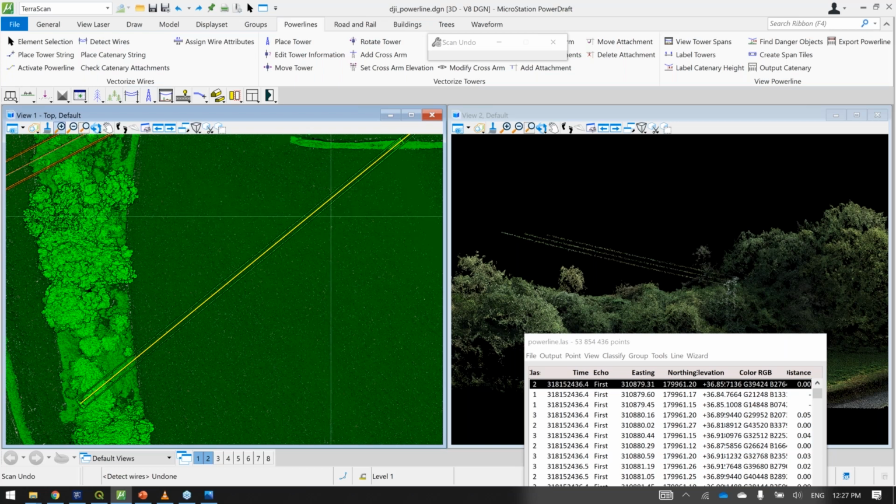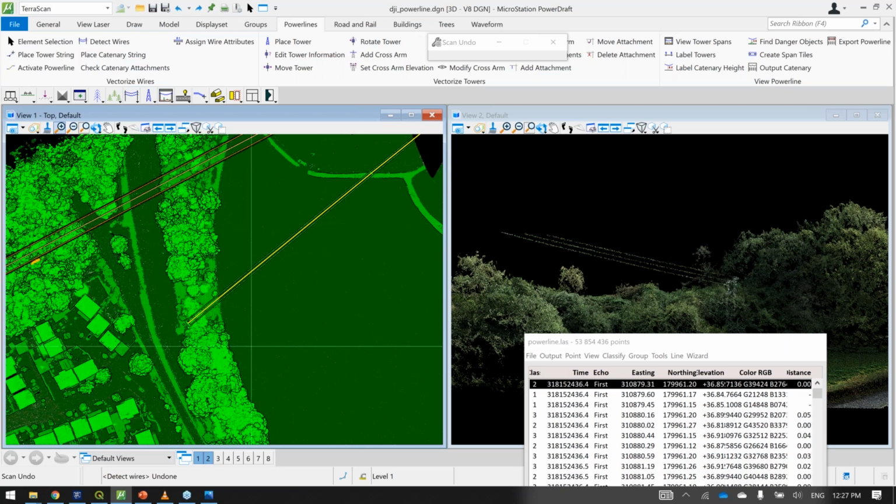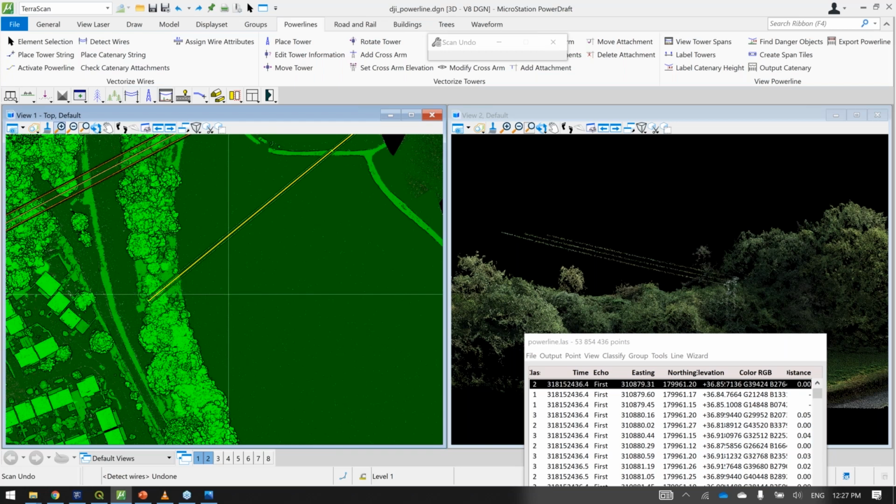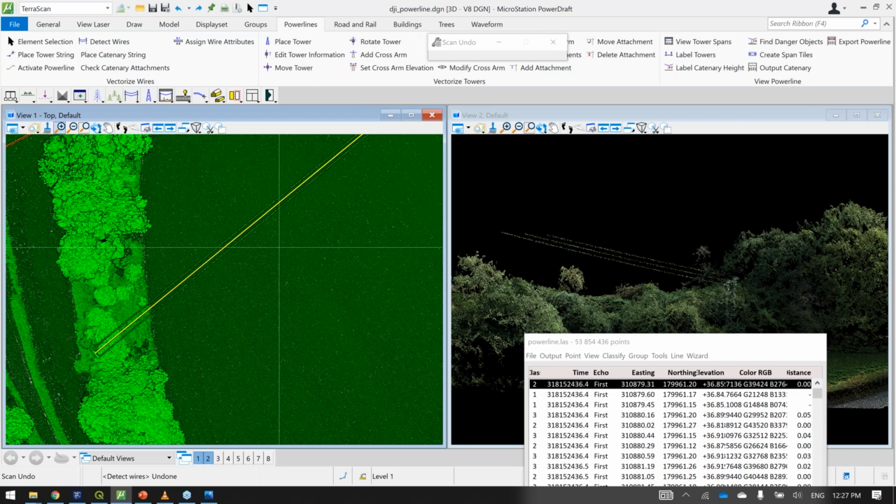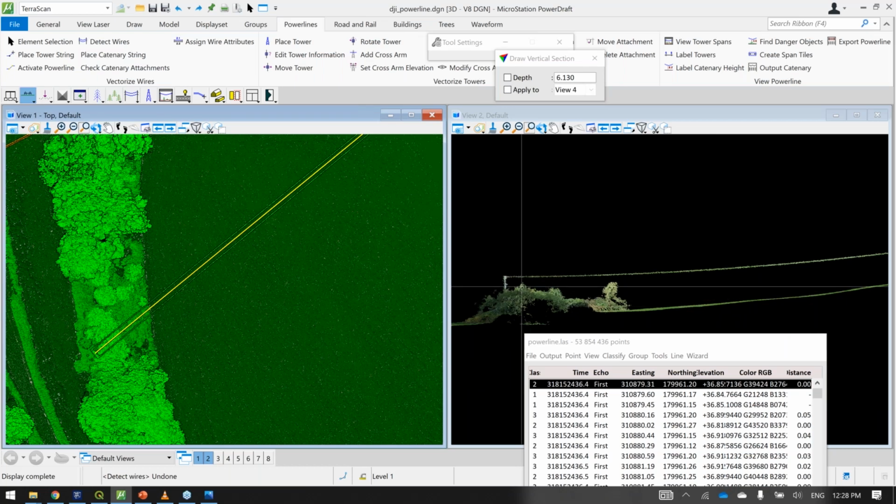So at the moment, I have the point cloud distributed into 3 classes according to the distance from the ground surface, and mostly the wire points go to the high vegetation class or to the class which is more than 5 meters above the ground, so as not to overload the step of detecting wires with the amount of data.